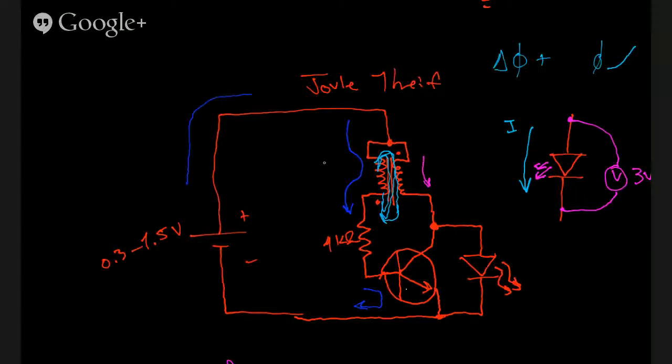Across here, our transistor isn't turned on. Actually, our transistor is on at this point, or is in the process of turning on. So the current following the path of least resistance will just drain back to the battery. And eventually, once this magnetic field inside our toroid, our little transformer here, is completely saturated, it'll turn this transistor fully on.